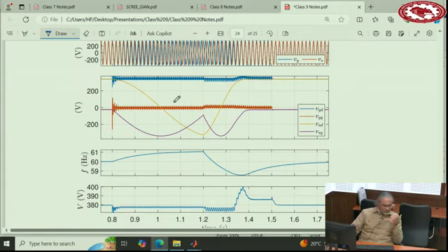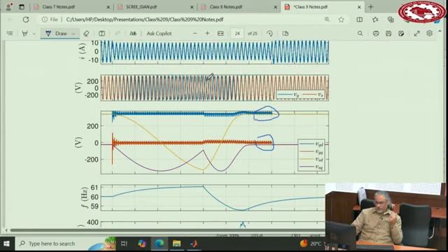Because we are working with the angle of the synchronous machine, from the synchronous machine's perspective the grid is going away, so it brings the grid closer to itself. It will push the grid back to itself. Now you are safe to connect back because these are closer. And even if you look at the voltage, you see these two voltages go closer and closer. Now it's safe to reconnect, and then there is a smooth transition, and the frequency will go back to 60.